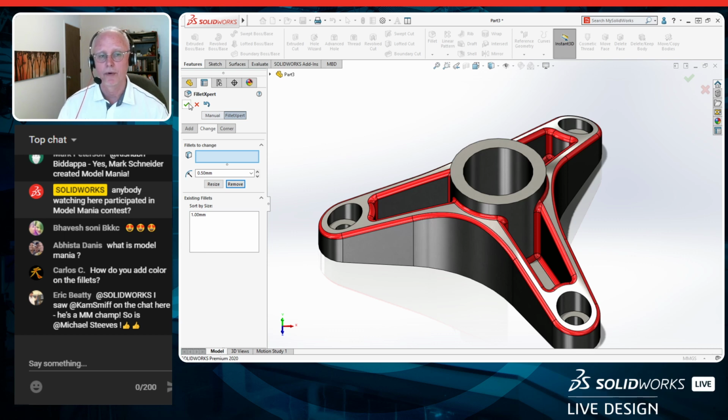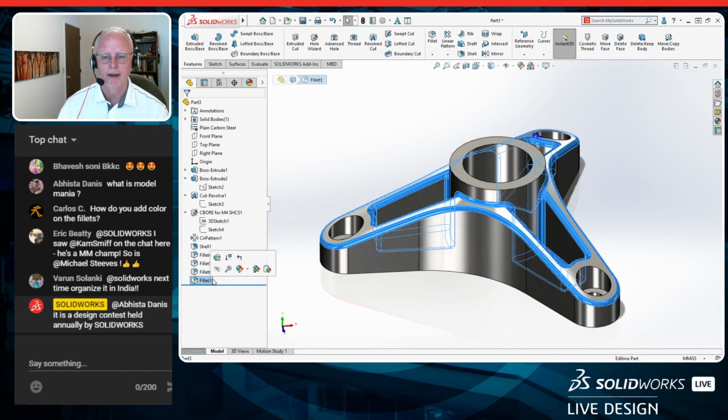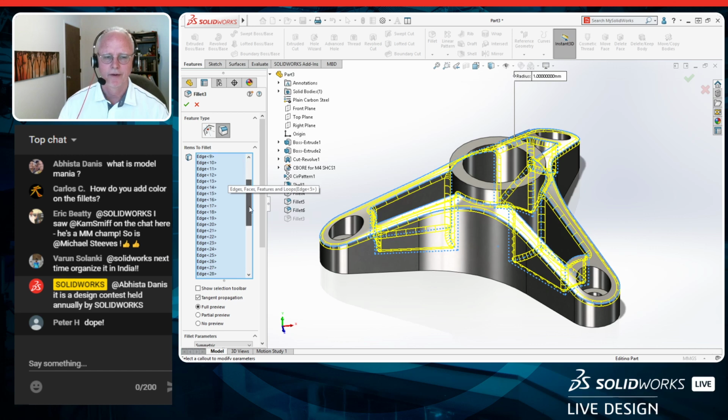So that's pretty cool, and if I go ahead and accept that, then I have my part as I want it. The only problem with that is what it does to your model. Remember, we chose a feature to fillet. So now I have all these edges, and if anything changed in my geometry, if something moves something around, some of these edges might change, some of the faces might change.